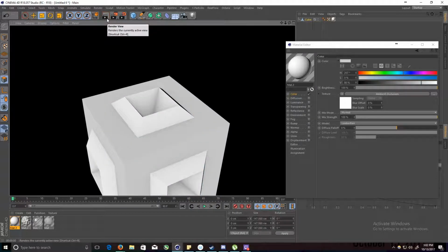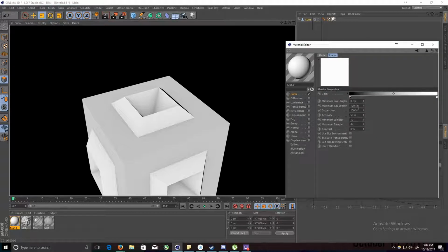Okay. So if I take this model right here and put an ambient occlusion filter on it, you can see here with no lighting or texture or color or anything, I have these shadows at the edges and in the pockets, and that's from this ambient occlusion shader. It's basically doing the same thing a render engine would do when it's calculating ambient occlusion, ray tracing edges and seeing where there are tighter hits, and it's adding detail there. And you could use an ambient occlusion shader, this black and white texture that's being generated, to drive another texture.